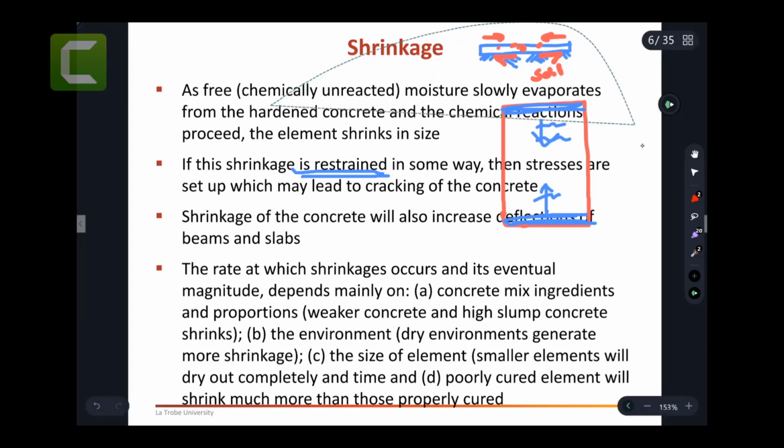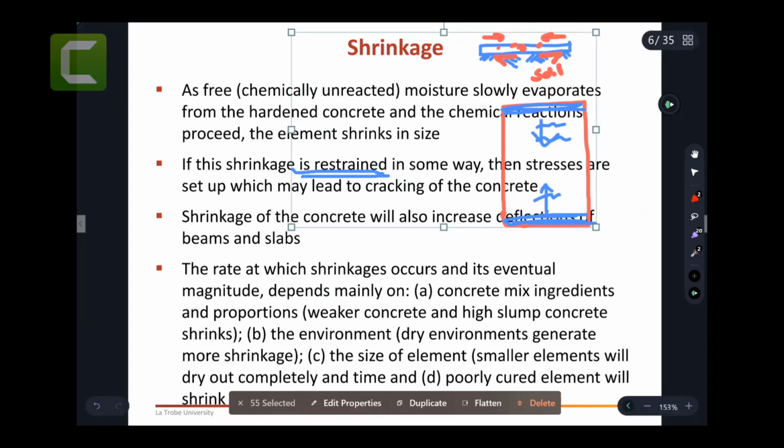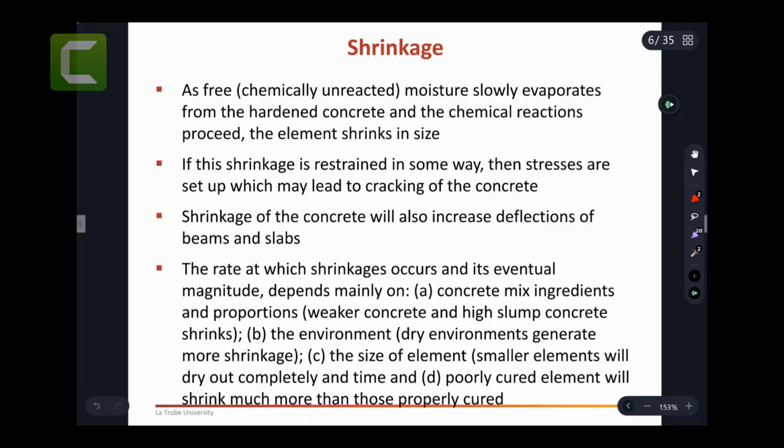We can't put a lot of reinforcement, so we also employ sockets. I'm talking here about slab on the ground. However, for suspended slabs, we cannot make sockets. We don't do that. We do movement joints, and this is a different topic which I don't want to get through. So for suspended slab, you're never going to make sockets. You do something different called movement joints.